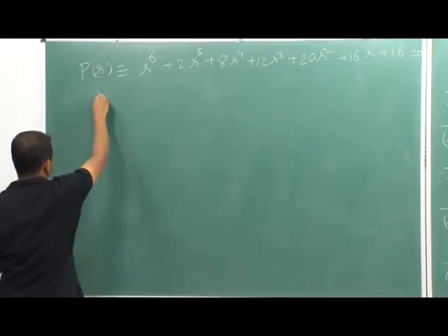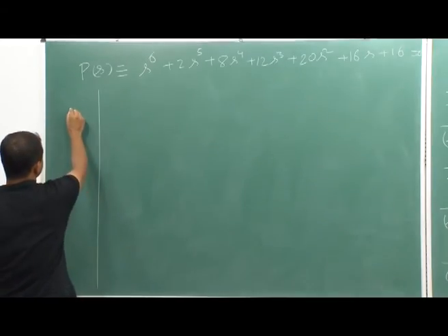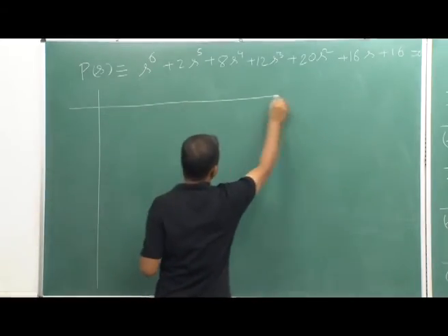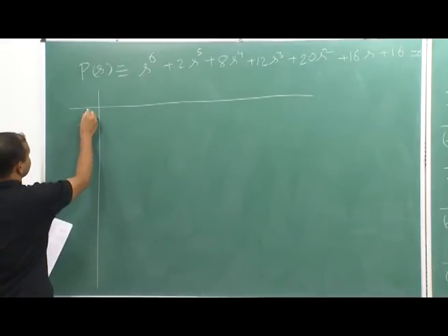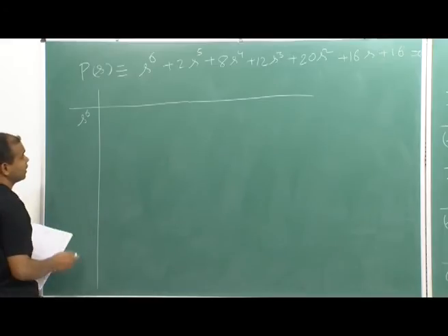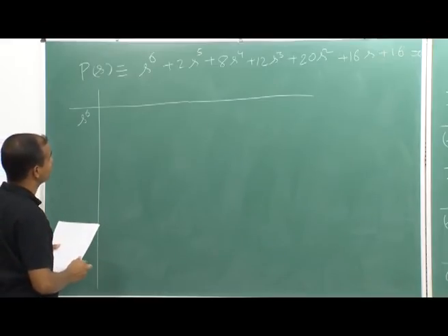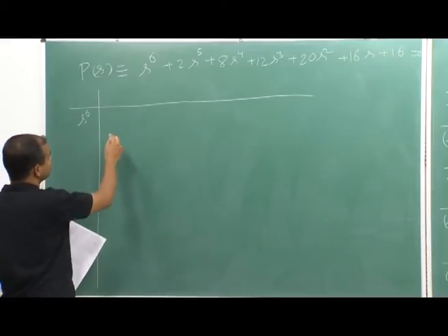If I construct the Routh array, the highest power is s to the power 6 and this is even. So, I will write all the coefficients having even power of s in descending order.